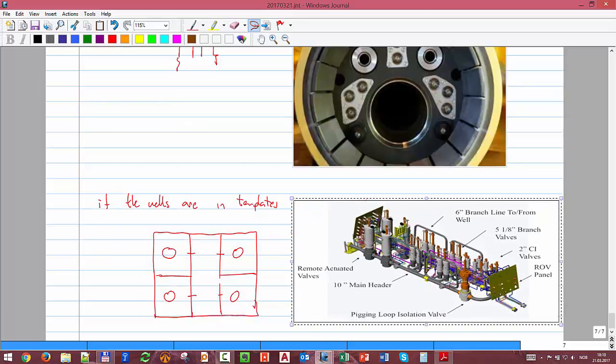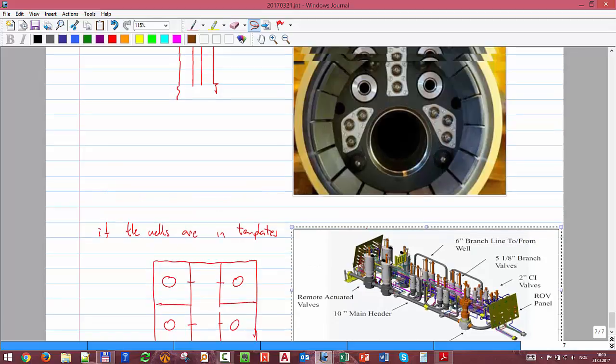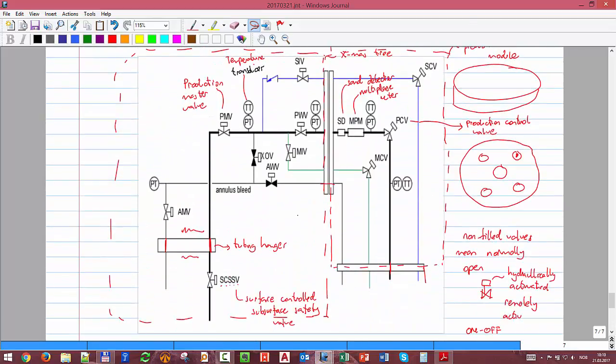What is the function of pressure, temperature transducers? Well, for many reasons, but basically you want to know what the wellhead pressure is. Remember, for us production engineers, wellhead pressure is extremely important. So you have pressure, you have redundancy. That equipment will be there for maybe 10 years. So if one gets damaged in one position, you still want the other one to be functioning.